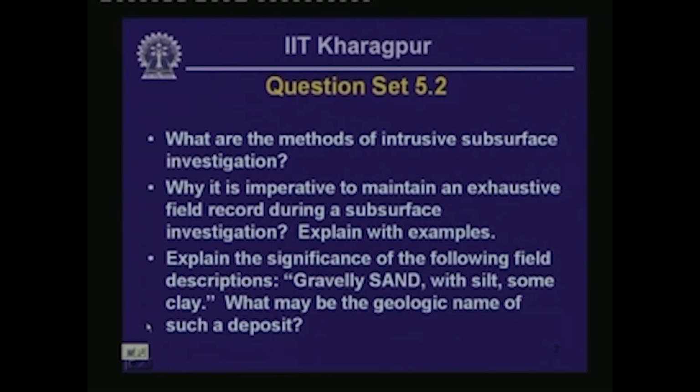The first question that I asked was what are the methods of intrusive subsurface investigation. Basically, in the discussion of this particular course, we just talked about two basic procedures. One is excavation of a pit or a trench in the ground for exploration of shallow layers underground, and the second group of procedures that we discussed are based on drilling a circular hole in the ground and conducting some sampling exercise.